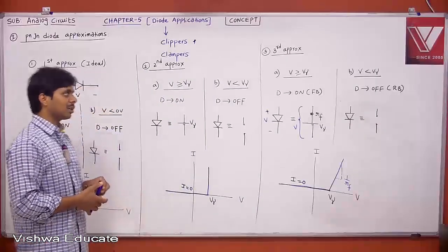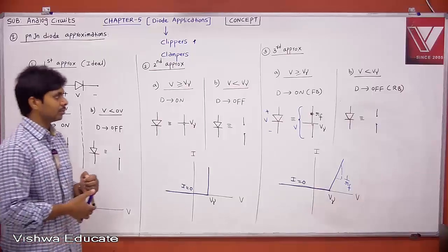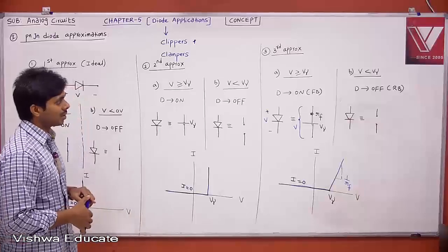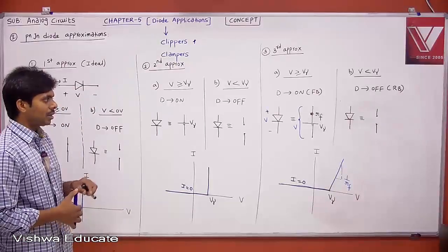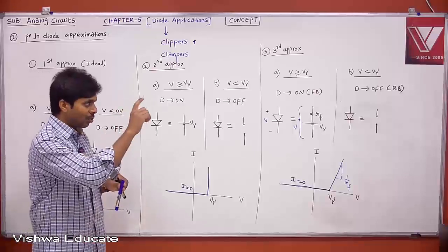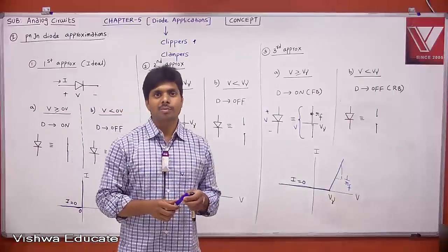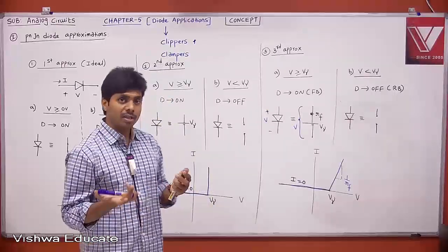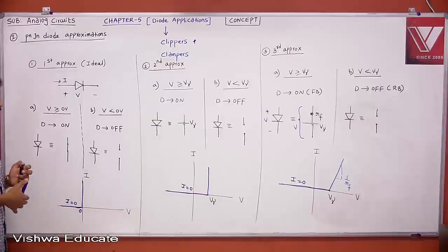That is your dynamic resistance or internal resistance of your PN junction diode, which is not constant, strictly speaking. It depends on your bias because it is a non-linear element. For all non-linear elements, the dynamic resistance value or the slopes depend on the operating point. If the operating point changes, the slope changes, meaning resistance changes or gain changes. All AC parameters will depend on your operating point.